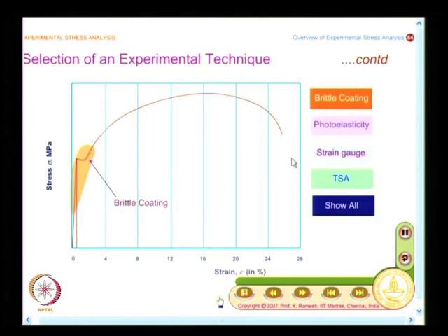And when I say photoelasticity, what does it indicate? I am essentially living in the elastic region. So, a photoelastic analysis will confine only to the elastic region, it will give you information. If I have to go for the plastic region, I have to go for photoplasticity. Currently, we are only looking at photoelasticity. And the moment you come to strain gauge, we have seen you have techniques which can measure even 0.5 microstrain.